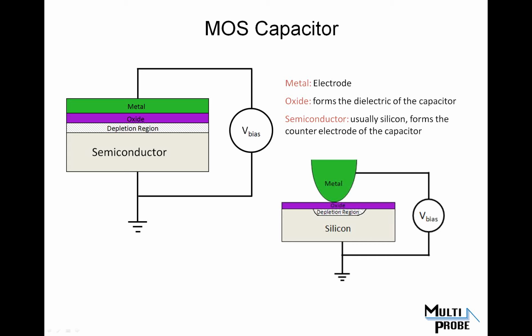So this is a little primer on scanning capacitance. There's a gate and a semiconductor region and some oxide or dielectric between them. As you change the bias on the structure, you create a depletion region, which effectively changes the capacitance or the plate spacing, because as you bias the semiconductor, either you deplete it out and so the capacitor plates essentially move apart, or you accumulate it so all the charge is tucked up underneath the gate, and so you get a higher capacitance.